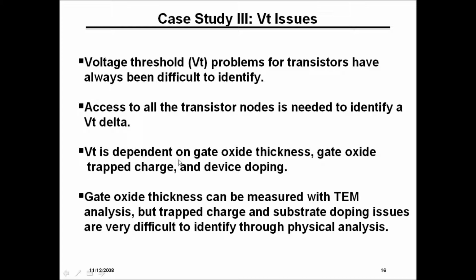But VT is dependent on gate oxide thickness, gate oxide trap charge, and device doping. That's traditional VT. Gate oxide thicknesses can be measured with TEM analysis, but trap charge and substrate doping issues are very difficult to identify through physical analysis.